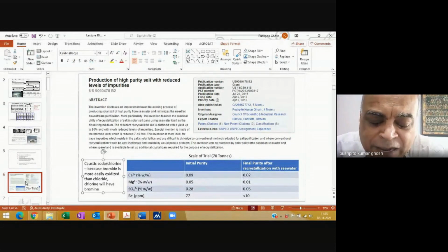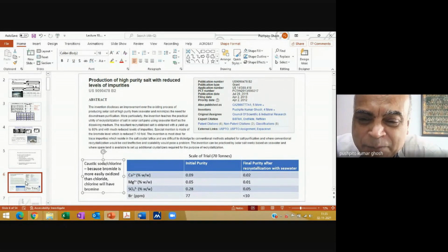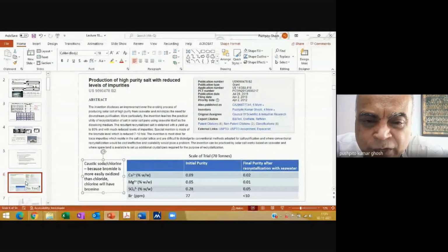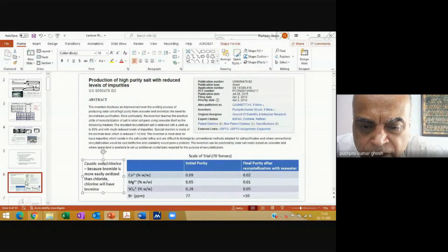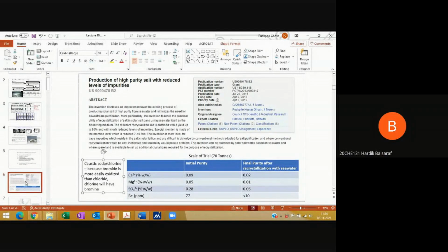Stirring. There are well-known methods of doing stirring in the field. There are people who use paddles, and you can do it. And you see, it's not like a factory. Residence time is not so critical. I don't have to dissolve it in 5 seconds. In the field, I don't care. Even if it dissolves in 1 hour, I'm okay. Things which are very critical in the plant may not be so critical in the field. So it will require manual labor and a lot of time.